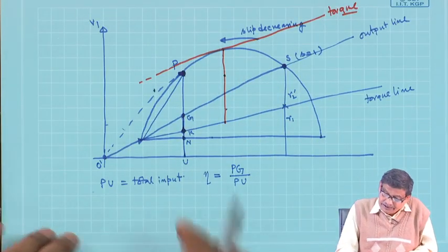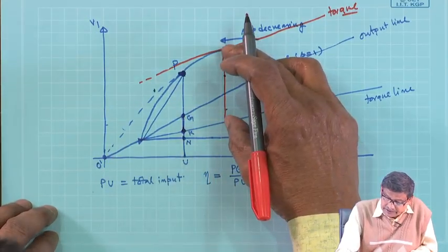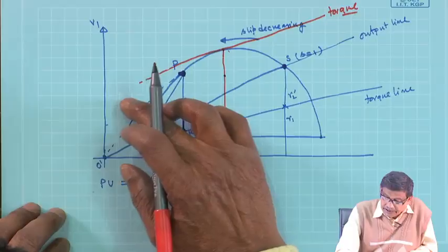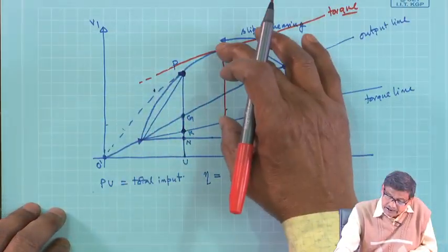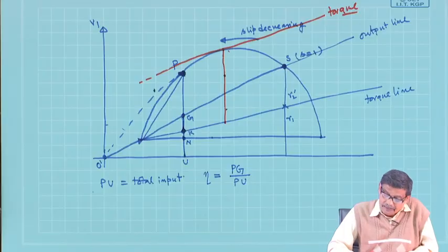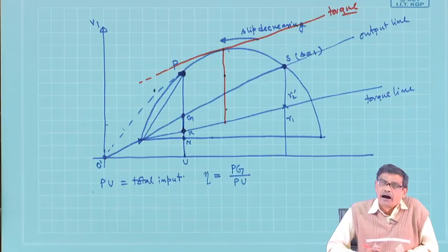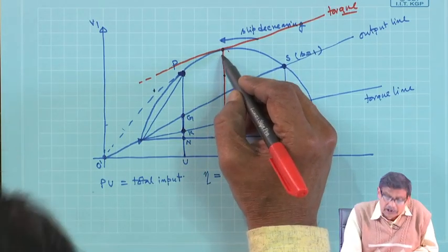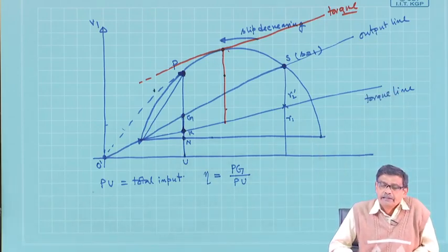So, this intercept will be maximum when the operating point is such that, if you draw a line parallel to this, only then this segment is maximum. Similarly, if somebody says I want to get output power maximum, from this I will calculate back this slip and tell okay, the machine is operating at this slip.